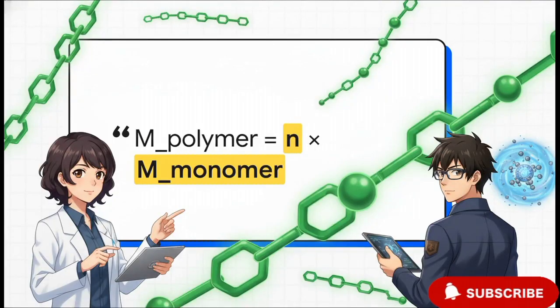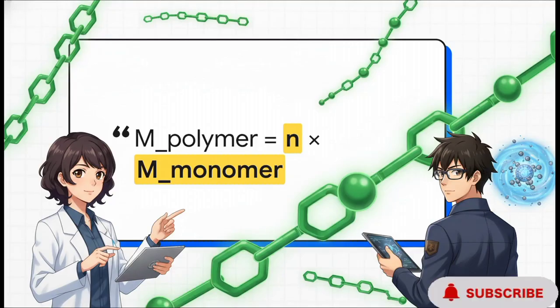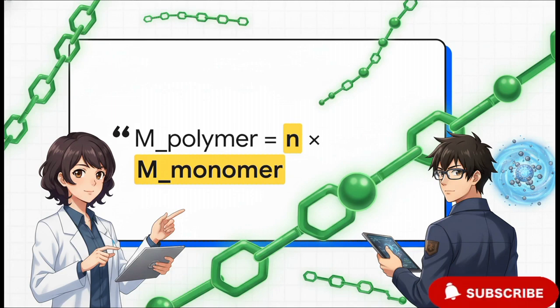Engineers actually use a really simple equation for this. And hey, don't let the math intimidate you, the logic is super straightforward. The total molecular weight of a polymer is basically just the number of repeating links in the chain, that's the N, multiplied by the weight of a single monomer link. That's it. Engineers can literally design a material's physical properties just by controlling N, by deciding exactly how long these molecular chains get to be.